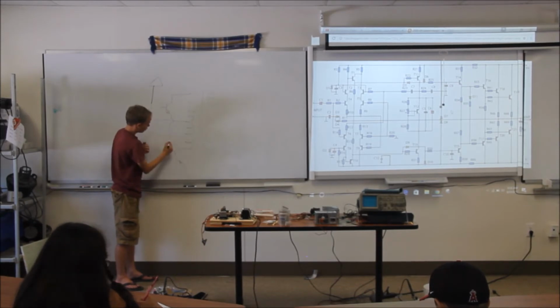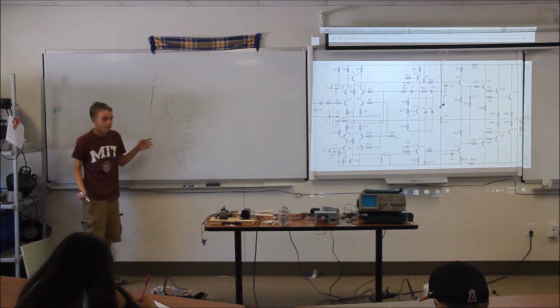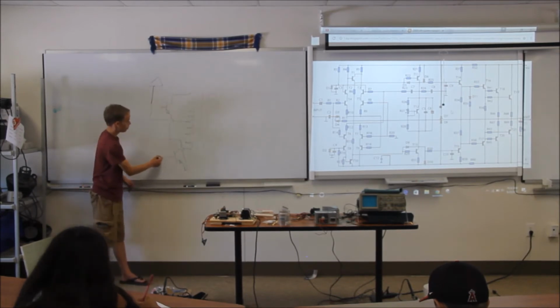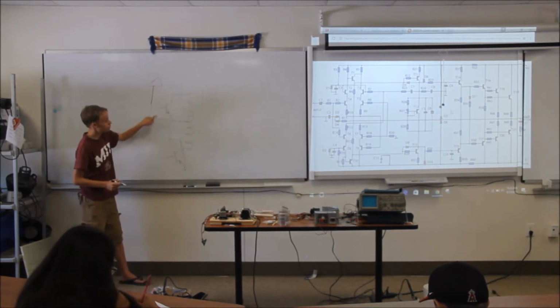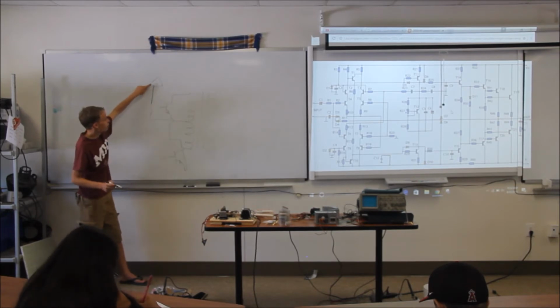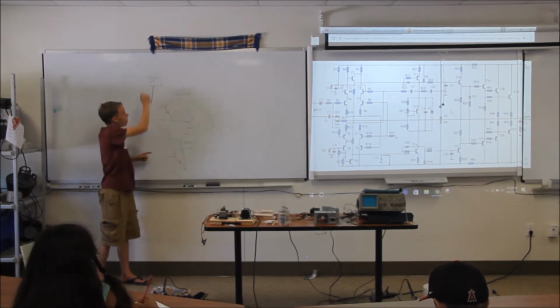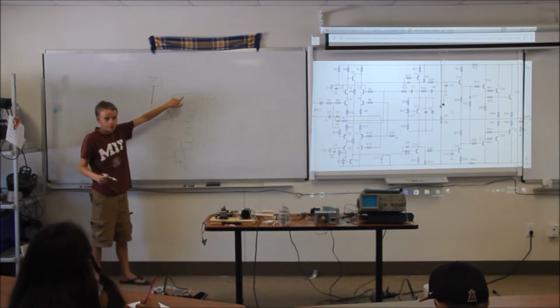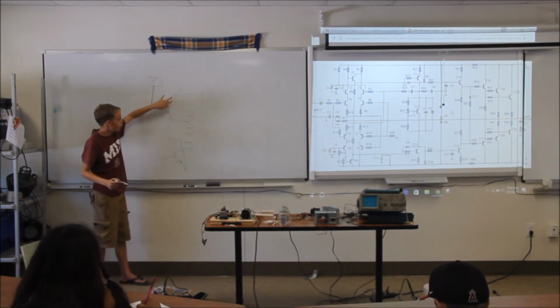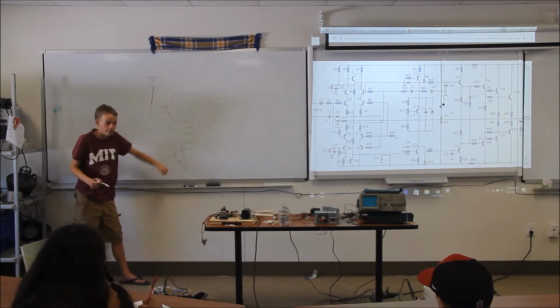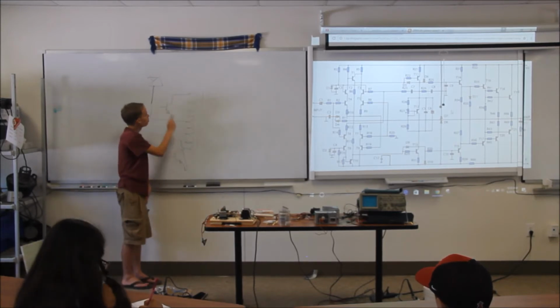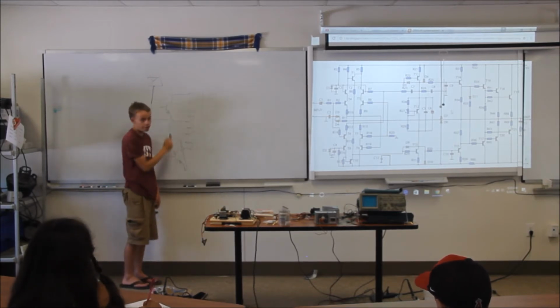Okay, so both of these transistors are now grounded. So that means if we apply a voltage to the base of one of these transistors, then it's going to allow the current to flow from positive through this coil of the transformer, through the transistor and back to ground. Now the current can flow in two directions depending on which transistor is activated.